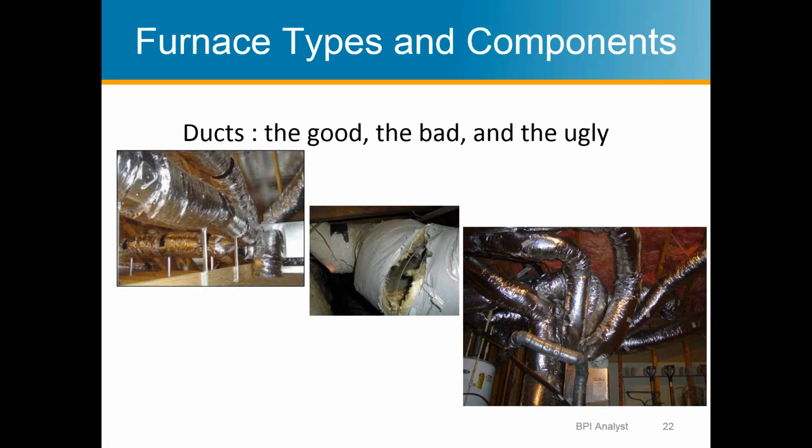All right, so here's just the good, the bad, the ugly of ductwork. What you want in ductwork is nice straight runs. You want very little resistance in the flow of air through your ducts. So long straight runs, as opposed to the spaghetti that you found down here.